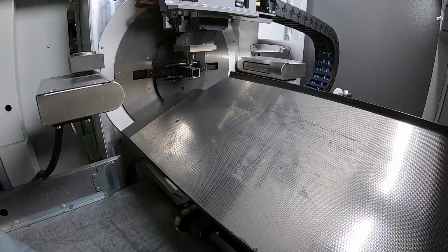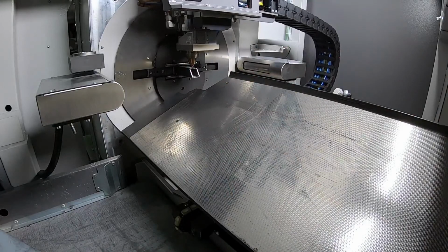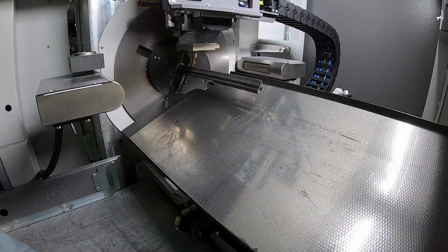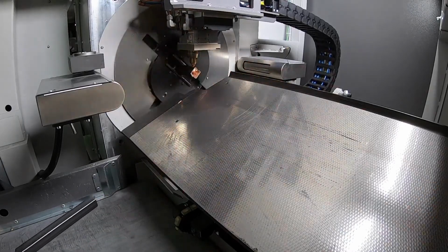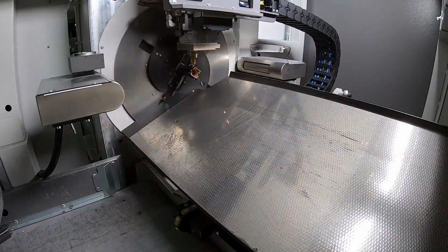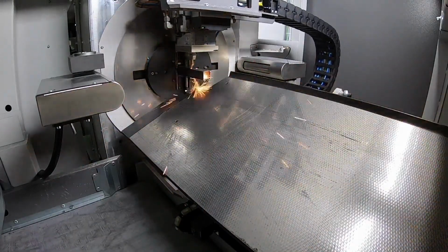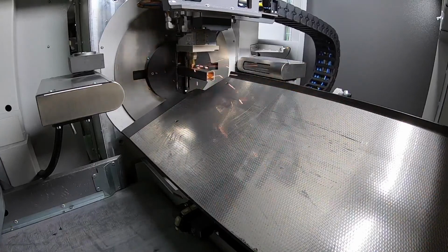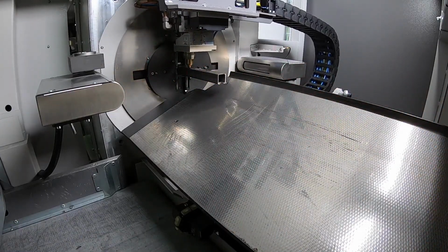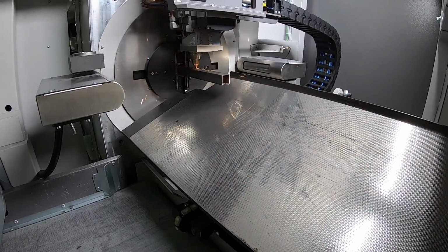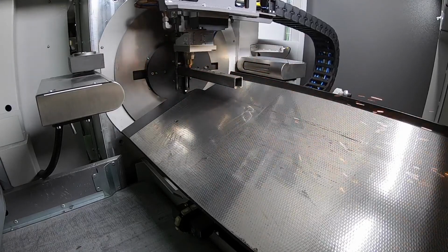Another important feature inside this machine is called laser scan. So we have those two silver boxes on the sides of our tube, and this system is scanning with two laser beams the tube shape, and according to tube shape and tube bending, we will position the head exactly in the center of the tube. So it will compensate the bending of the tube, and it will always guarantee us 0.2 millimeters of tolerance during the whole system. All the procedure will be completely automatic, so you don't need to do anything.